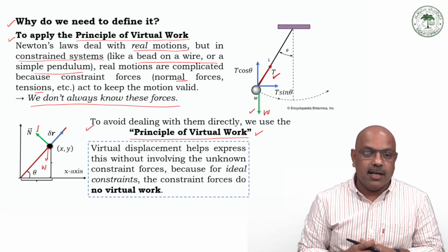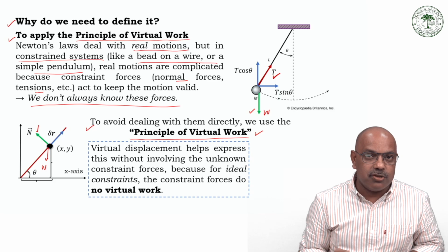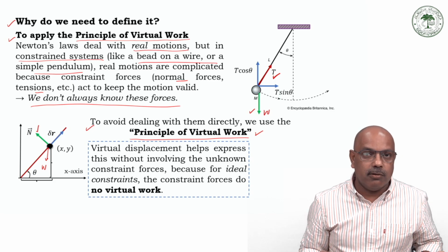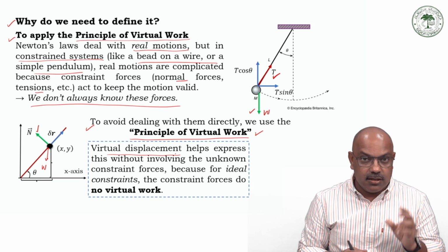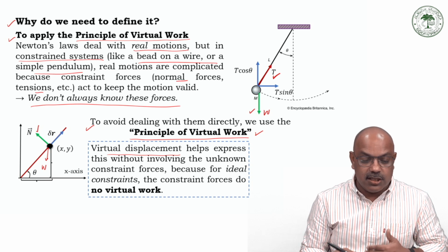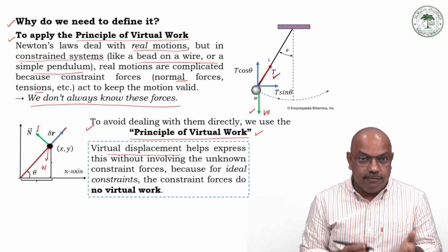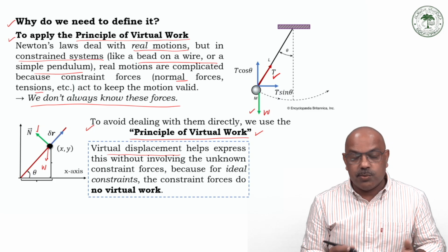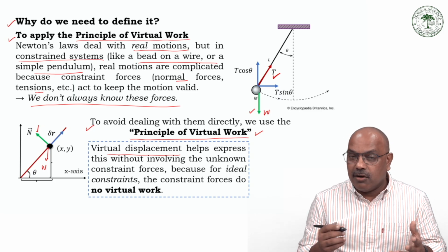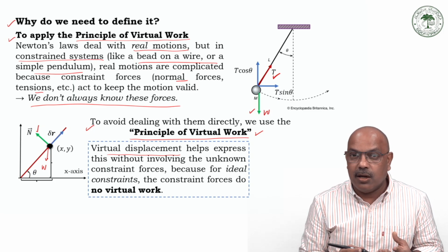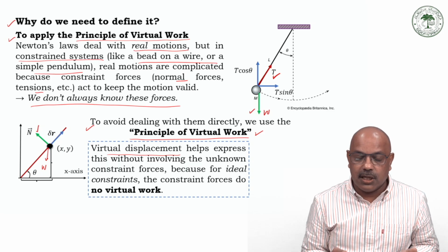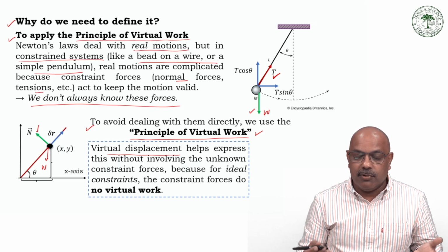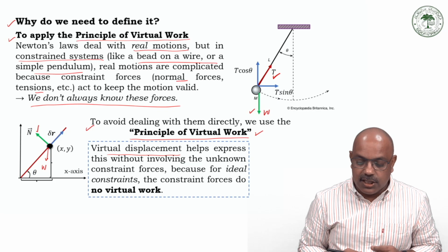When you're talking about work, there has to be displacement. When you're talking about virtual work, there has to be virtual displacement. So the concept of virtual displacement is introduced to define the principle of virtual work, and the principle is introduced to get rid of all those forces which we don't want, so we don't complicate our system.